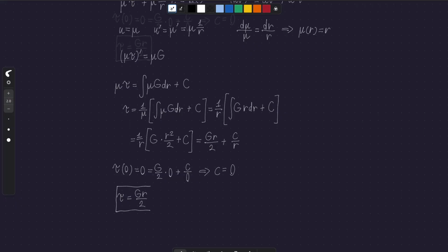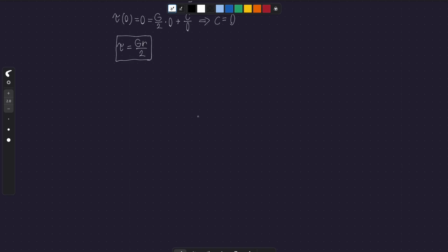Okay, now that we have this formula, we can start to find the formula for the pressure drop. Just for a warm-up, I'm going to start with a Newtonian fluid, and we will derive the well-known Hagen-Poiseuille equation. The shear stress of a Newtonian fluid is given by this formula, which is Newton's formula for the viscosity. Basically what it says is that the shear stress is proportional to the shear rate with a constant term, which is the viscosity.